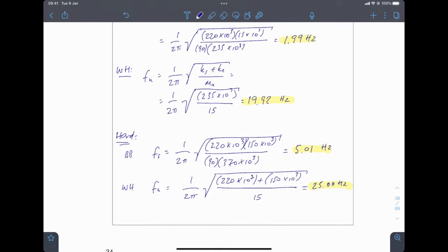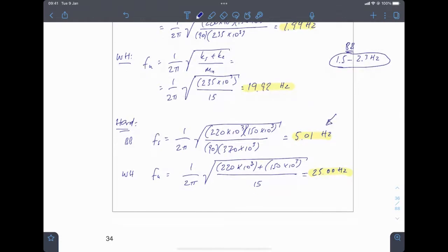Interesting, with ride, you want something generally between 1.5 and 2.3 hertz for body bounce to be comfortable, because this frequency matches your natural gait as you walk along. Your body is conditioned to find that relatively comfortable. If you go above 2.3, it starts to be quite uncomfortable, and certain frequencies will induce nausea. Other frequencies, your eyes won't be able to focus on a single point.